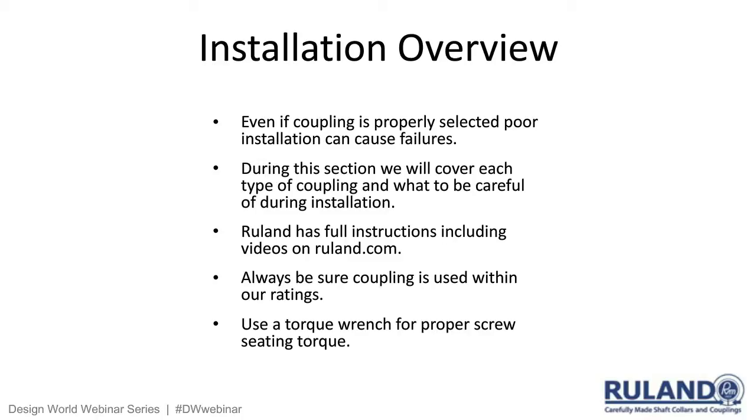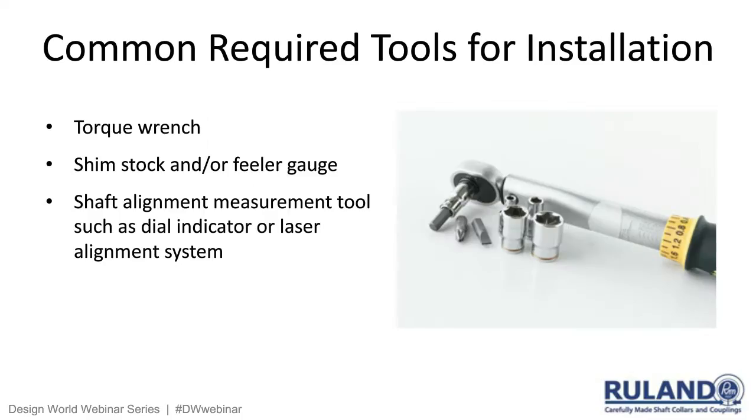Always be sure the coupling is used within our ratings. Use a torque wrench for proper screw seating torque. Common required tools for installation: torque wrench. It's really important to use a torque wrench when you're tightening screws on couplings.